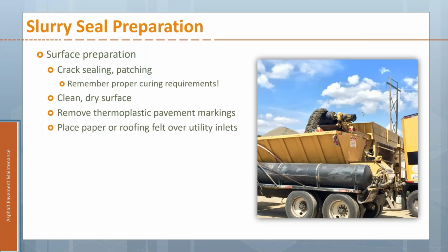Now, preparation, we've got to do any crack sealing, patching, anything. Because again, with something this thin, we're not going to be able to bridge any structural issues or cover up a lot of problems. So if there is a problem, fix it before you put the slurry seal on top of it.